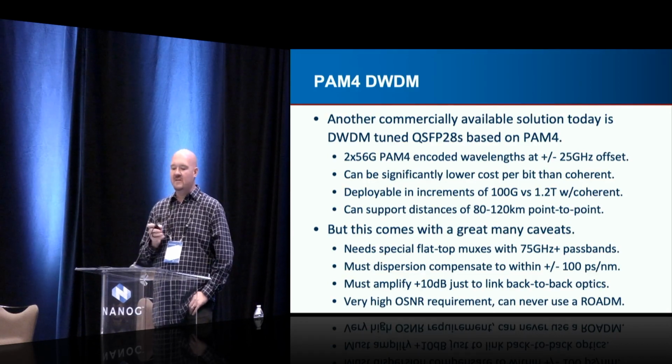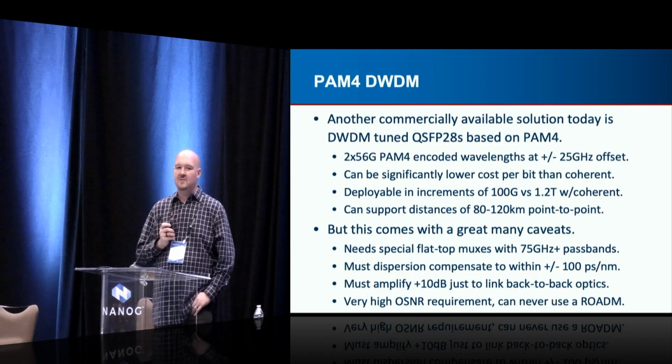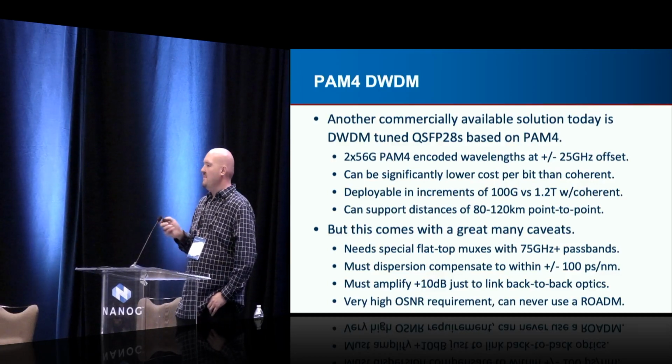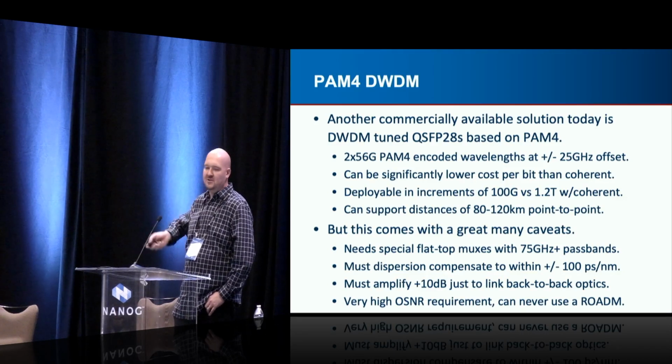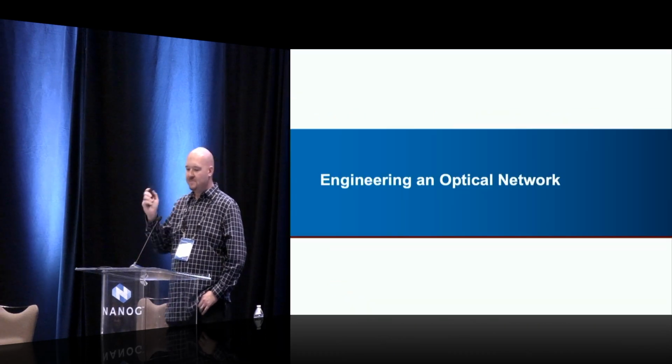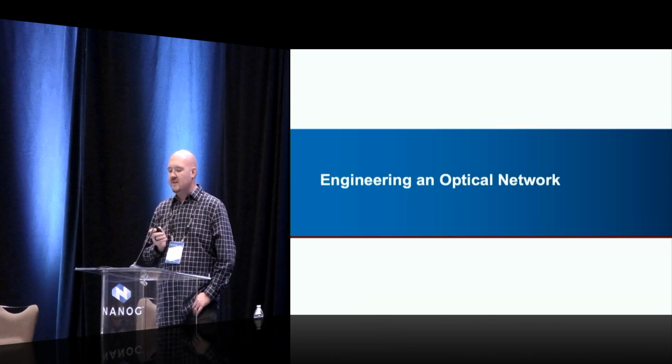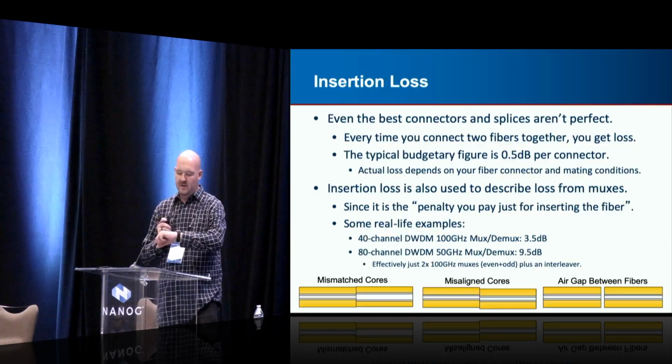And these things have a very high OSNR requirement. So basically you're never able to pass a PAM4 system through a ROADM. The impact from all the amplification is way too much. So now I'm going to talk a little bit about engineering that you can do.